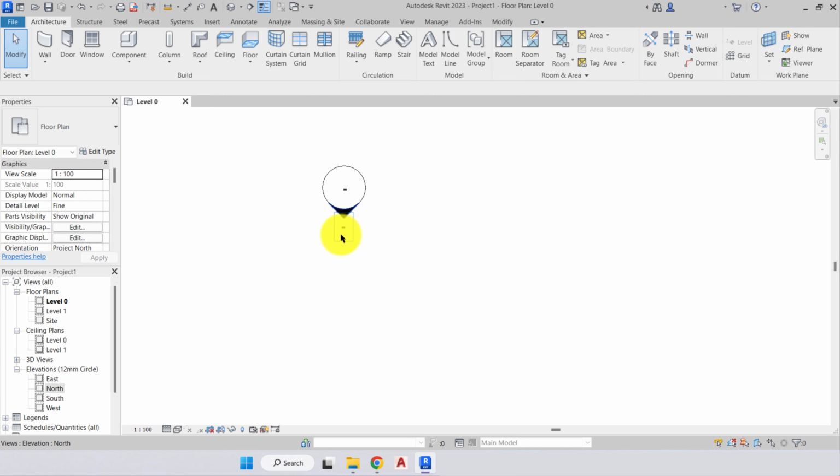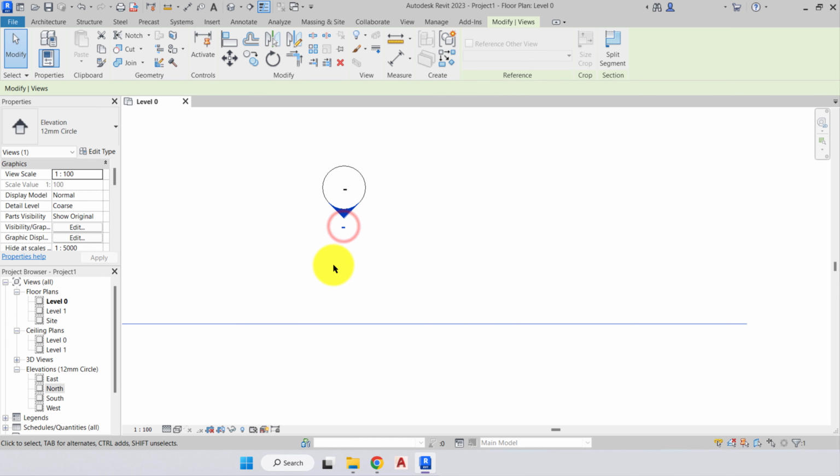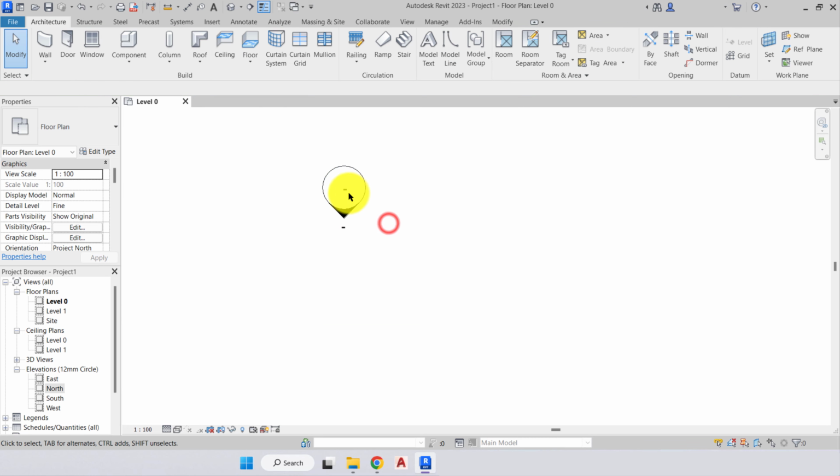The reason there is no information in here is because we have no elevation labeled yet, and we have no sheet number labeled yet. So when we add in a view name, it'll automatically update and be displayed here. I can't actually change that name or the top. But when we place an elevation onto a sheet, the sheet number will be displayed as well as the view number. So it saves us having to go back, relabel our views and add in the sheet number. As well, it totally eliminates any human error, such as missing one elevation so that the label is incorrect.